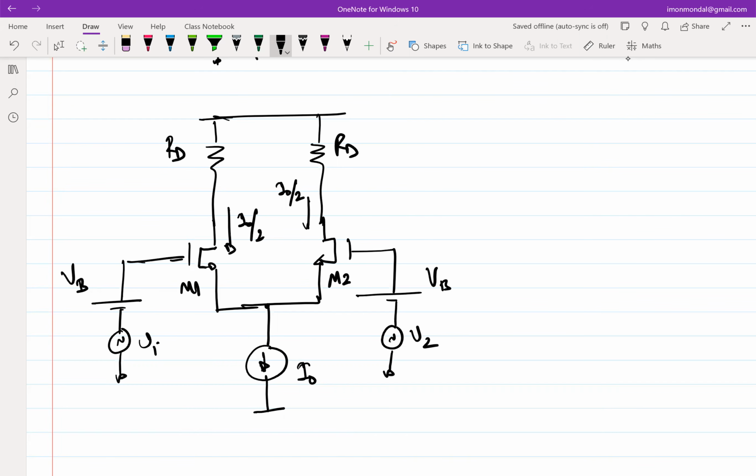So which means that we can get rid of the resistor with an active load. I assume that you are comfortable with the idea of the problems with a common source amplifier with resistive load. What is the problem? Why are we interested in replacing RD with an active load? Too much voltage drop. Right.